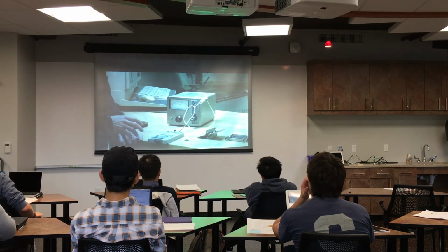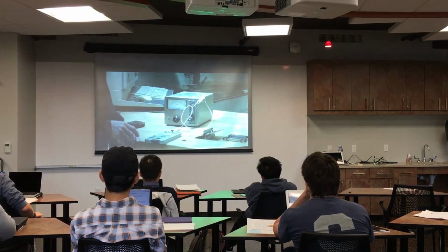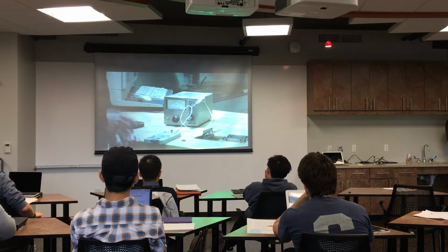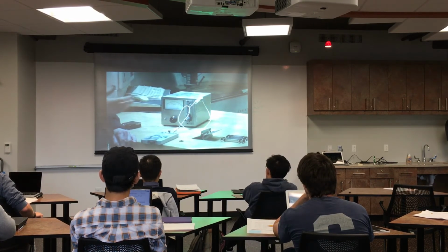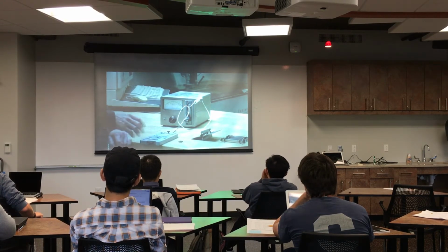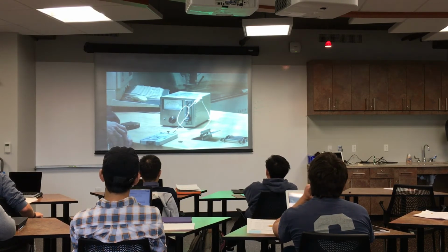Now this flexure is just a tutorial, so it's made of aluminum. Obviously aluminum is very temperature sensitive, about 22.6 ppm per degree, so you can't have aluminum if you want stability. In real life this would have to be cut out of Invar, or maybe some glass like Zerodur, or some other material that is very stable with temperature.